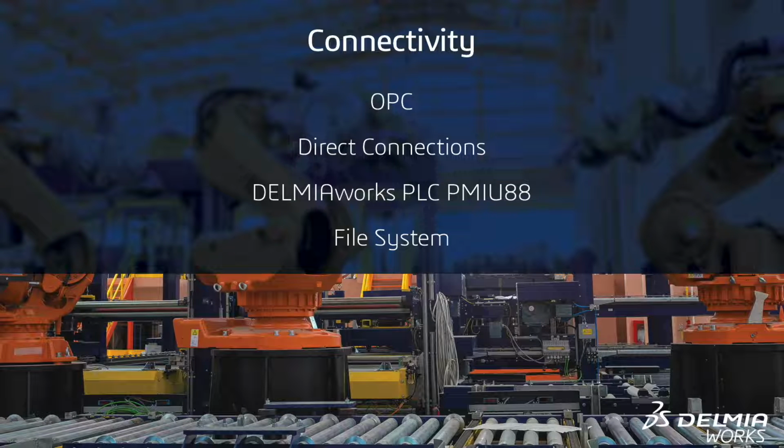The first being OPC. Real-time process monitoring can connect and integrate with OPC client-server compliant systems. OPC is a client-server technology and a leading widely accepted industrial communications standard. OPC enables the exchange of data between OPC-compliant industrial field devices and applications. The OPC server is a software program that converts the hardware communication protocol used by a PLC into the OPC protocol. Most new industrial systems are OPC client-server compliant.